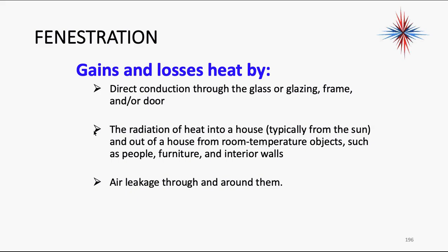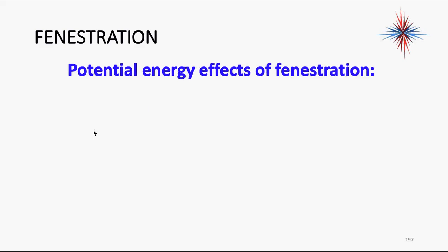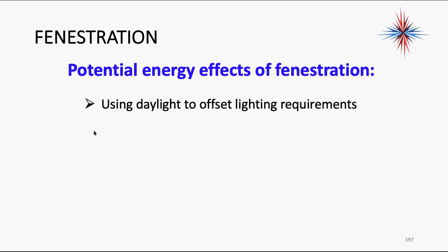Air leakage through and around them. Very few windows are extremely tight unless they're brand new Energy Star capable windows. There's going to be heat loss and gain around the windows. So we have some pretty significant energy effects of fenestration.